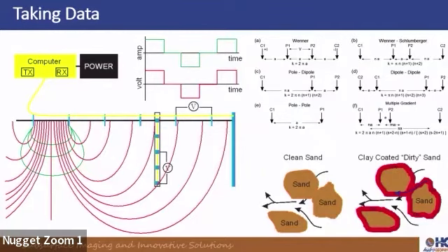And this is a little bit of a schematic of how electrical current passes through porous media. It can go through the pores where they're interconnected with the amount of water, and if there's more water between the pores, then you get more electrical current transfer. Or, most soils and porous media have some sort of clay, so we can also get electrical current passing through the clay.